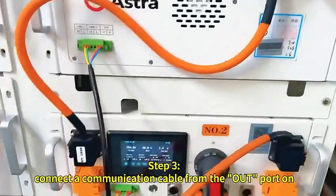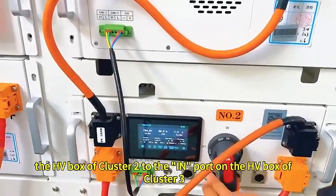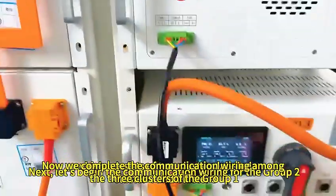Step 3. Connect a communication cable from the out port on the high voltage box of cluster 2 to the in port on the high voltage box of cluster 3. Now we complete the communication wiring among the 3 clusters of the Group 1.